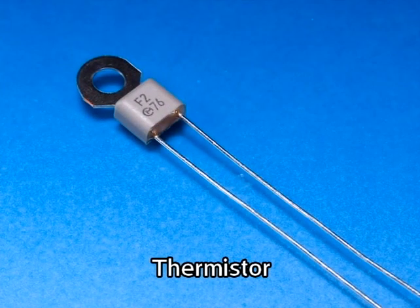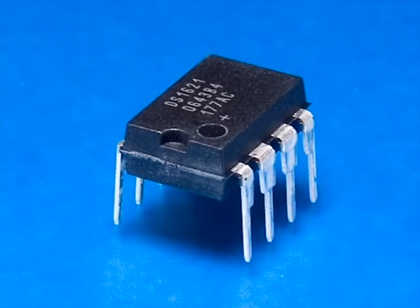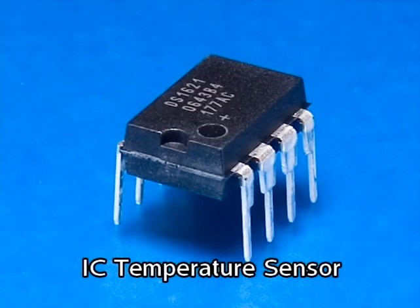A thermistor exemplifies resistance where the resistance value changes according to the temperature. This property is used as a temperature sensor. A thermistor is used in air conditioners, refrigerators, heater-overheat controllers, temperature warning devices, and so on. Since the IC temperature sensor uses a semiconductor as its temperature sensor, it can be included in one IC package together with the control circuit. It is both compact and very precise.